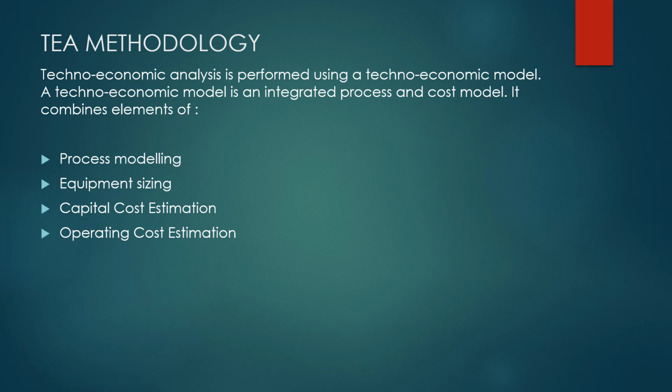They are typically estimated using a major equipment factor approach. So first of all, for example, in the chemical industry, we consider the purchase cost for each piece of equipment used in the industry. We estimate the results of the equipment sizing calculation, and then we apply multiplication factors based on similar systems to determine the capital cost estimation.